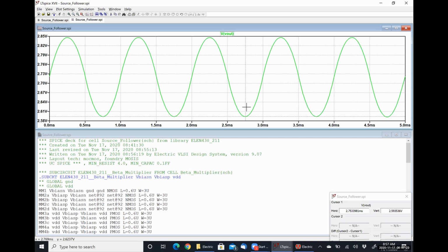I'm going to divide that by the peak to peak value of the input signal, which is 0.010 volts. So we have an overall gain of 25.26365. So it went from 26.8, I think, down to 25.3 effectively. But we have chained that guy there.